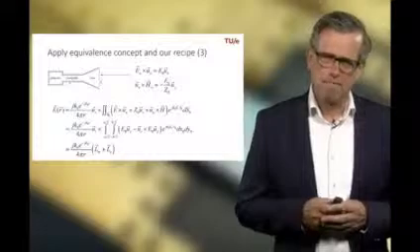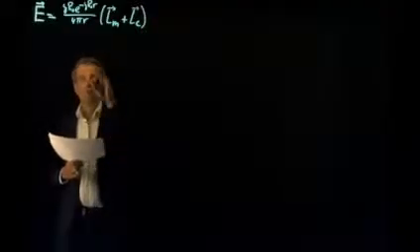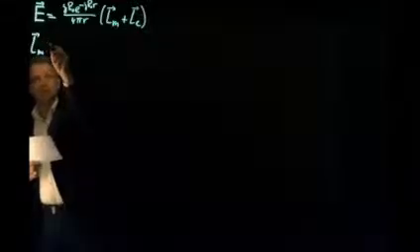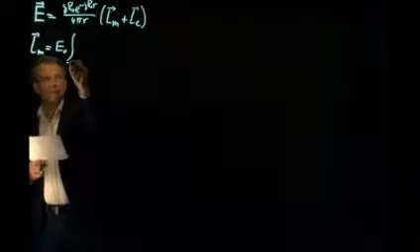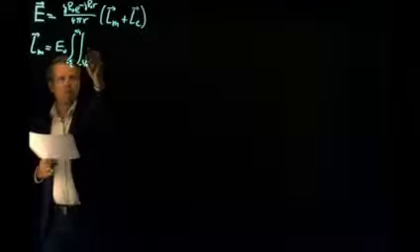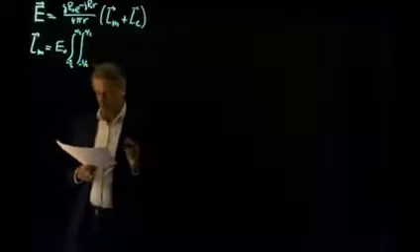Okay, so let's have a closer look at the expression for the far field, which consists of this spherical expansion of the wave times these two integrals that we need to work out. These integrals were given by, the first one, LM, was given by E naught times the integral over the aperture, where we assumed that the horn antenna aperture is centered around the origin of the coordinate system, by the way.